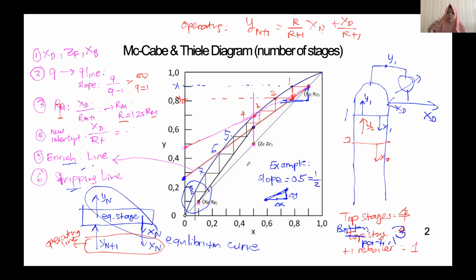So a typical question in the problem solving would be, for example, let's say I want to put a side stream when x equals 0.3, for example, this one in liquid form, in saturated liquid. What happens to the column? Will the bottom product have a similar composition, or what? What is the implication if I add a side stream there? Can you guess?